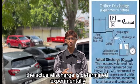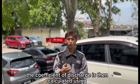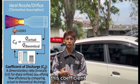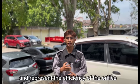The actual discharge is determined experimentally by measuring the volume collected over a specific period: QA = V/t. The coefficient of discharge is then calculated using CD = QA/Qt. This coefficient combines the effects of contraction and velocity losses and represents the efficiency of the orifice.